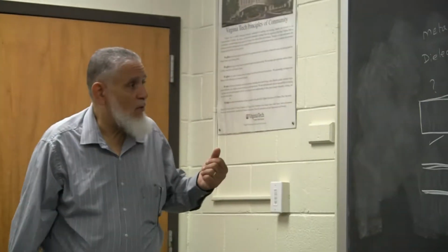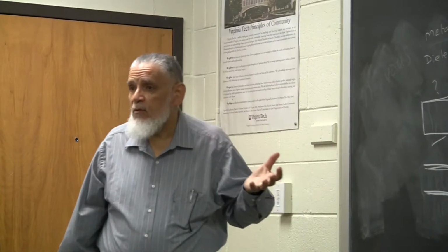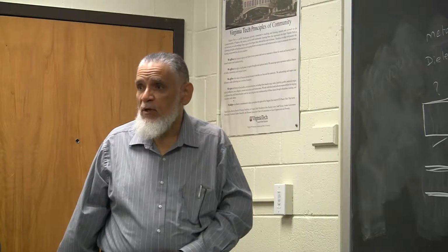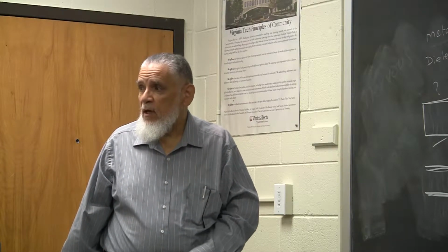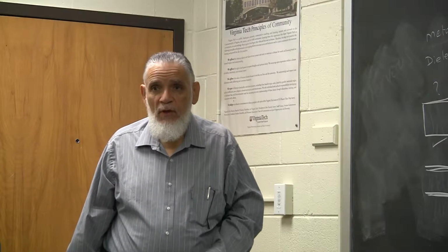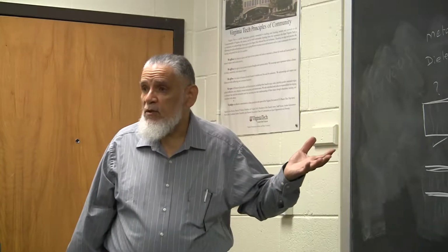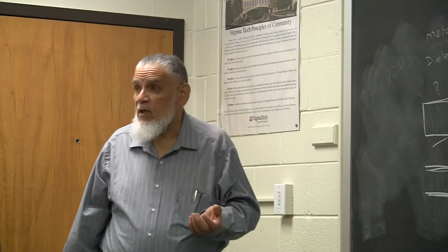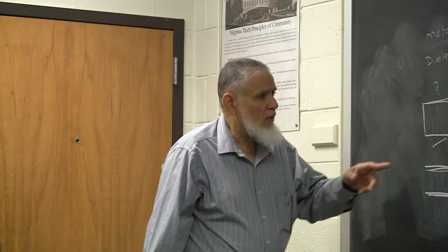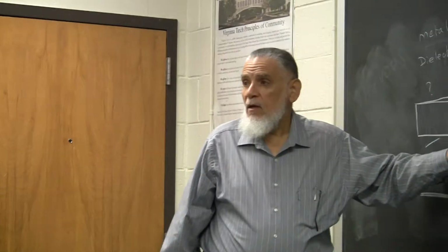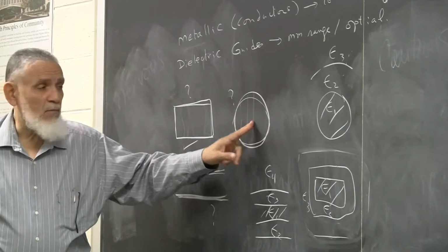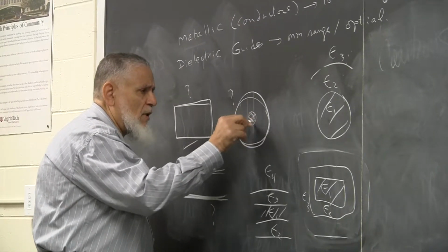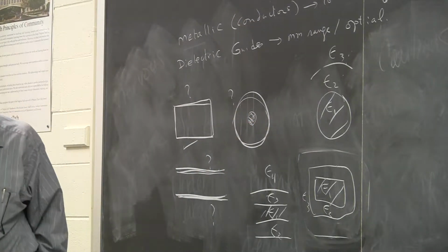Right? So what we do is we do the right thing, which is start with field analysis. We start with Maxwell's equations, we write the equations, and we solve those differential equations, apply the boundary conditions, and we get the solutions. And that's actually what we should be doing also with transmission lines. But if I do the circular one, it will be a step towards that, because all I need to do is add the center conductor and my boundary conditions, and I get the transmission line solution.